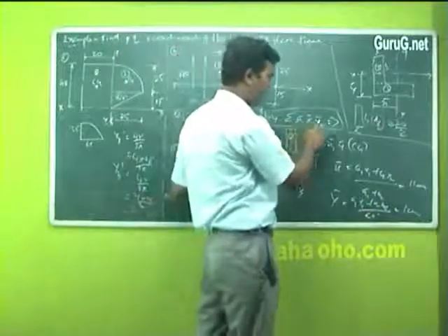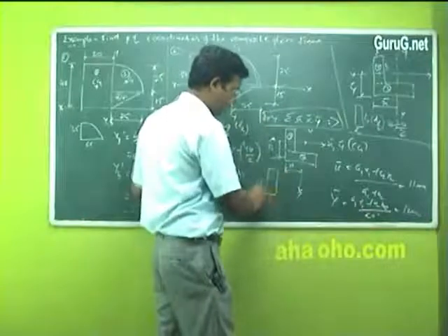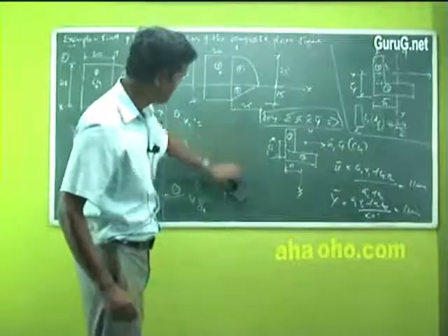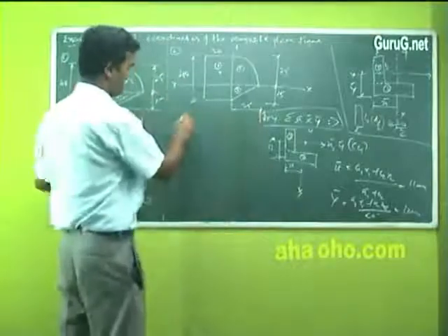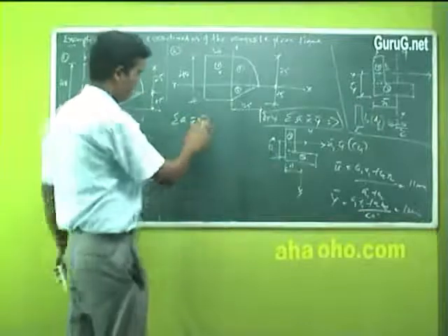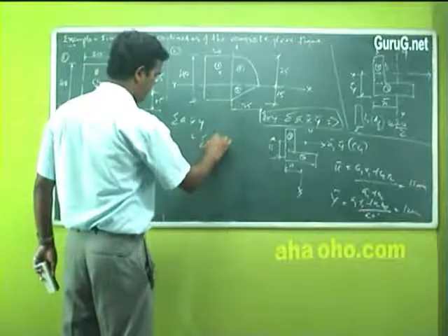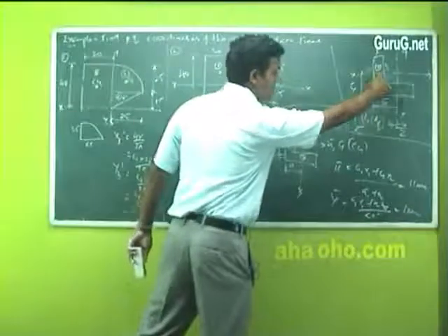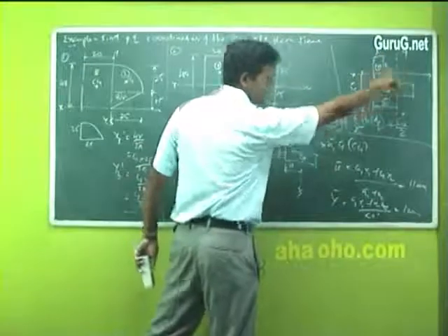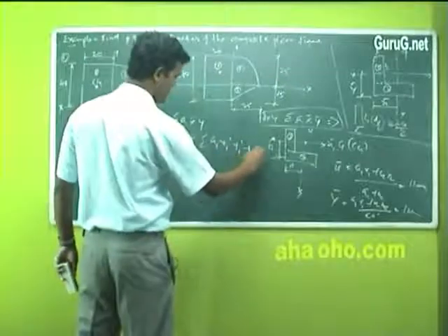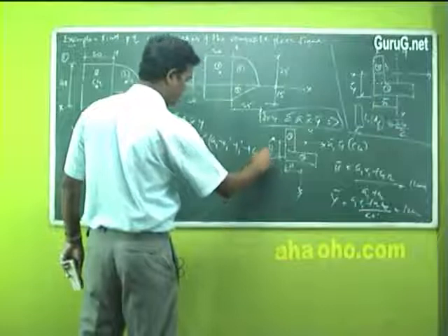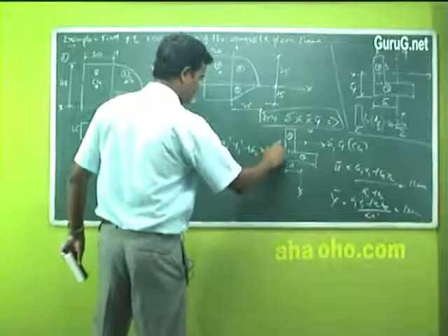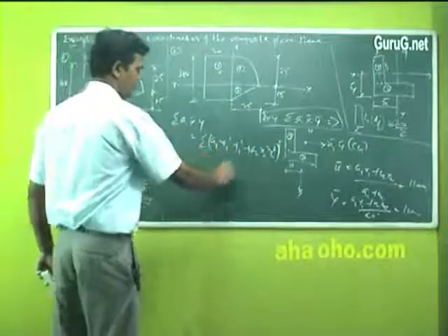So I am talking about x bar and y bar and area if you have only one sketch, say only one rectangle. But when my sketch is like this, it can be modified. The product of inertia, sigma a x bar y bar, will be sigma of a1 x1 dash y1 dash, that means you find x1 dash for this and y1 dash for this coordinate, plus a2 x2 dash y2 dash for the second. That's it, summation. You just multiply and get the answers.